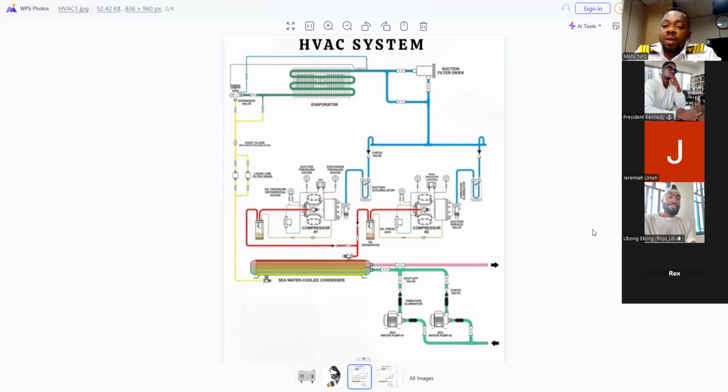I'm not sure the sensing bulb will make liquid return to the compressor. The only thing that will make liquid return to the compressor, practically and based on our lecture, is this: don't forget the evaporator blower helps to expel the coolness to the interior of your cabin, and further helps the liquid refrigerant change state from liquid to gaseous.